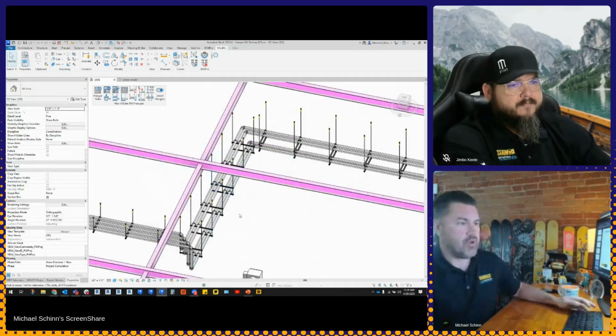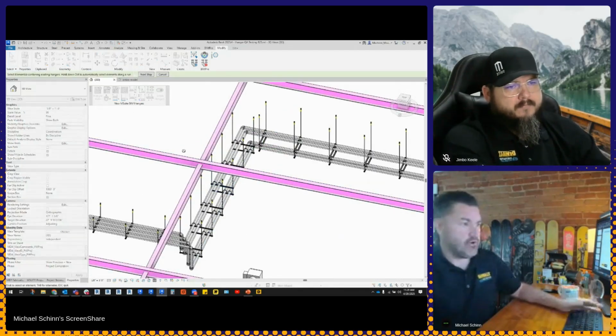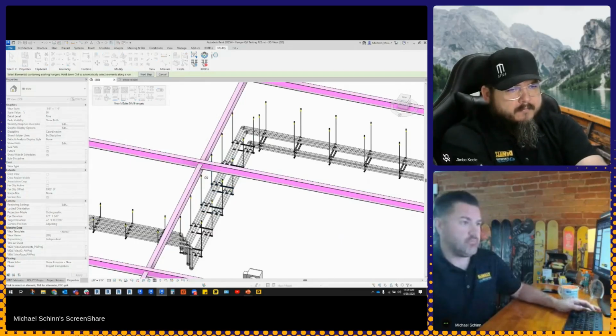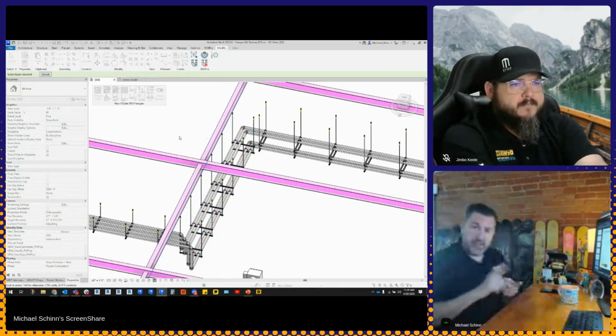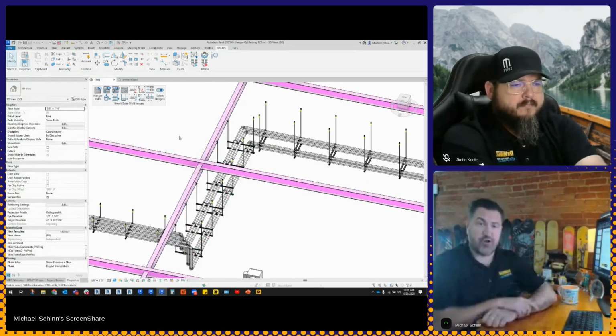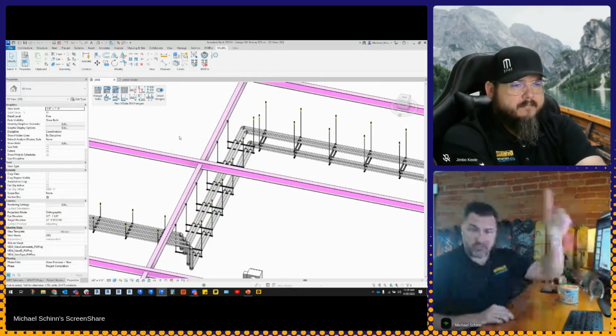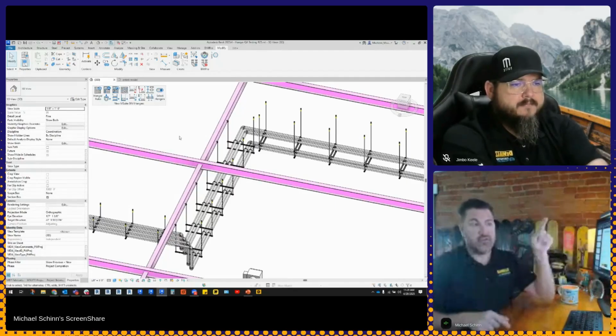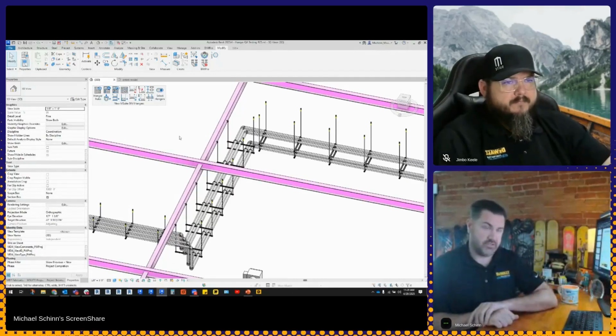We hit undo, put our screen back to where it was. So again, you can add this. I want this run. Click next. I want you attached to that structure. That works. Remember, we're not limiting this to just the steel that's drawn in your model. So you can do your supplemental steel, draw that across, and connect to it. This also works with your linked models.